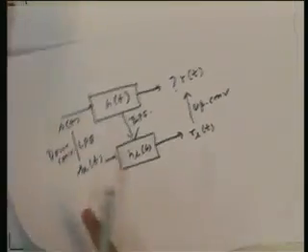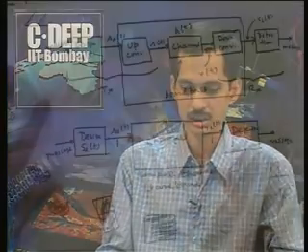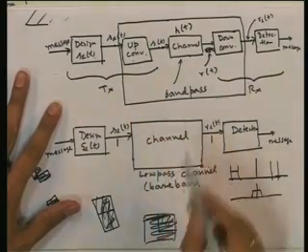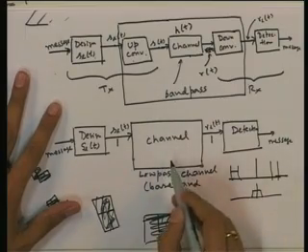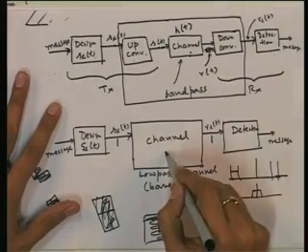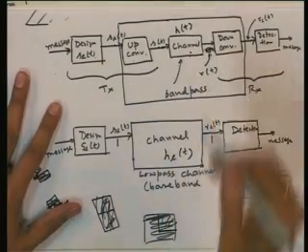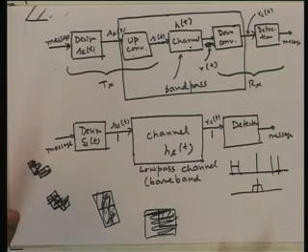because this is a low pass system. Okay. So we had seen in the last class that we can represent this up conversion channel and down conversion as a single channel, as a low pass channel. Now we know that there is a relationship between this channel and this channel. If this channel has impulse response h(t), this channel has the impulse response h_l(t), which is the low pass equivalent of this impulse response. So this is something interesting. This is what we have seen.